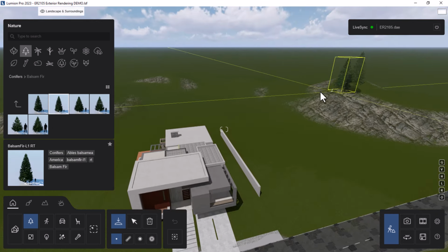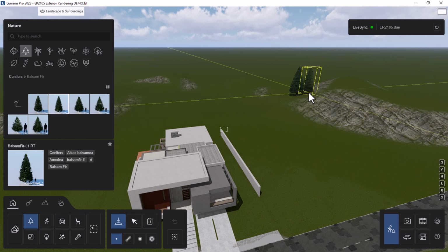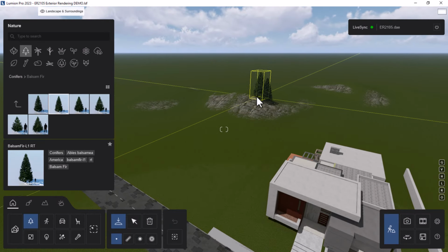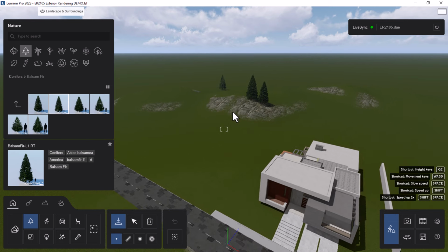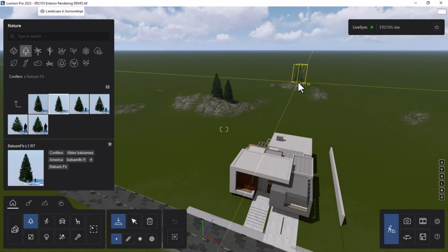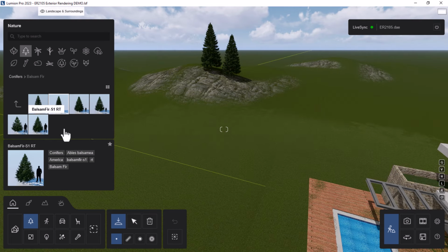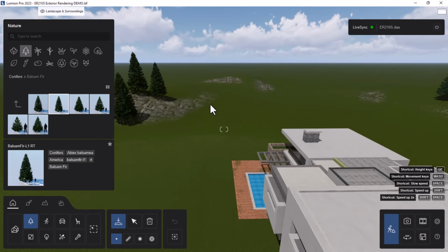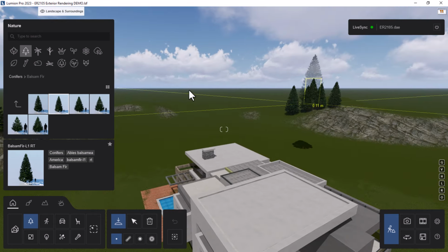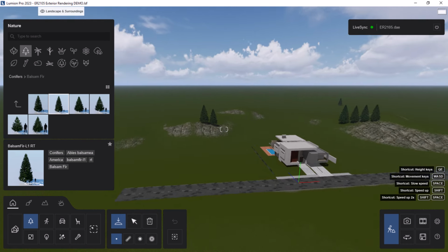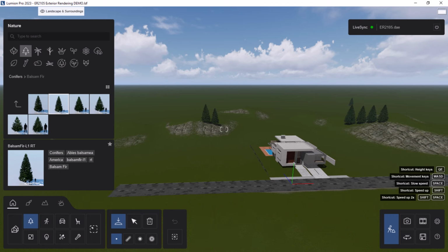All right, I'm going to place this, maybe 4 of them there. The side, place 2 of them. The good part of ArchiCAD is that if you place them, you can randomly reduce the size. You see, these 2 trees are on the same tree object, but they are not at the same size, which is great, because when you're dealing with 3D visualization, you need imperfections, because that's what makes it real.